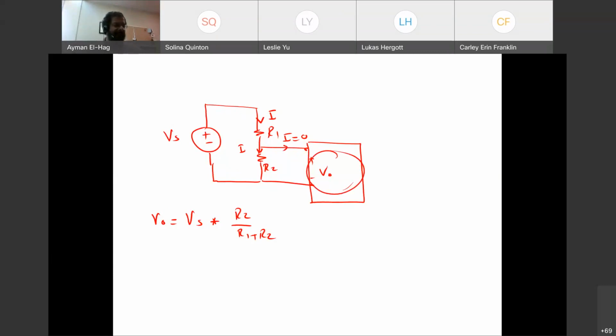I hope with this you understand the basics. I don't want to go into details, but this is what you want in any measurement system measuring voltage: its input impedance needs to be very high so that it will not load the circuit. Otherwise all the assumptions you have will be wrong, because the current that the circuit is consuming is significant.